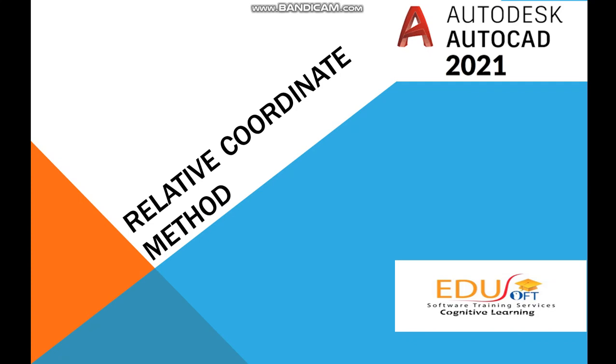In the absolute coordinate method, we had only one origin point where x is 0 and y is 0. But here, if we type @, the software will read the current position at which we are active as our origin point. If the distance is towards your right-hand side, the x value will be positive.